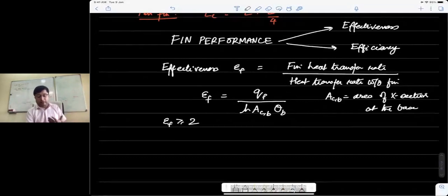If in industry you're doing this kind of analysis, you will actually go into much more detailed, maybe numerical simulations to calculate the heat transfer rate, so you will not take h to be constant. You can actually solve the momentum equation, the Navier-Stokes, and the energy equation to determine what would be h at that point. But we are doing this purely using analytical methods, so there we have to deal with h to be constant. So remember this, that there's a shortcoming of this method that I'm showing.